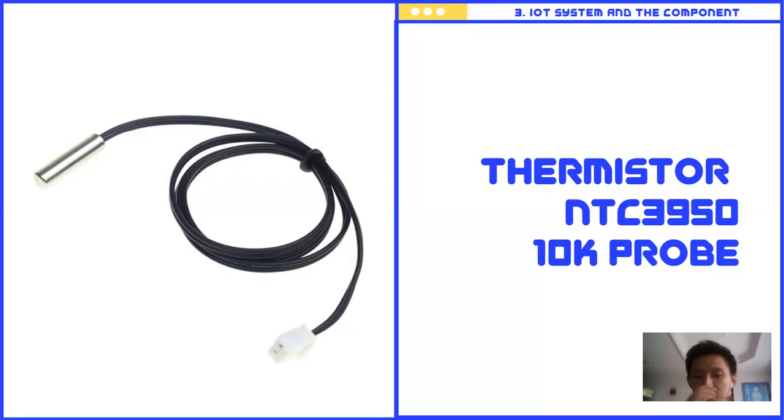Why do we use this thermistor? Because we also wanted to imitate the temperature sensor on the Caterpillar engine 7.1, and that sensor is actually analog. So we use this thermistor because it is an analog device, compared to the other temperature sensors like the IC or the others that work digitally.